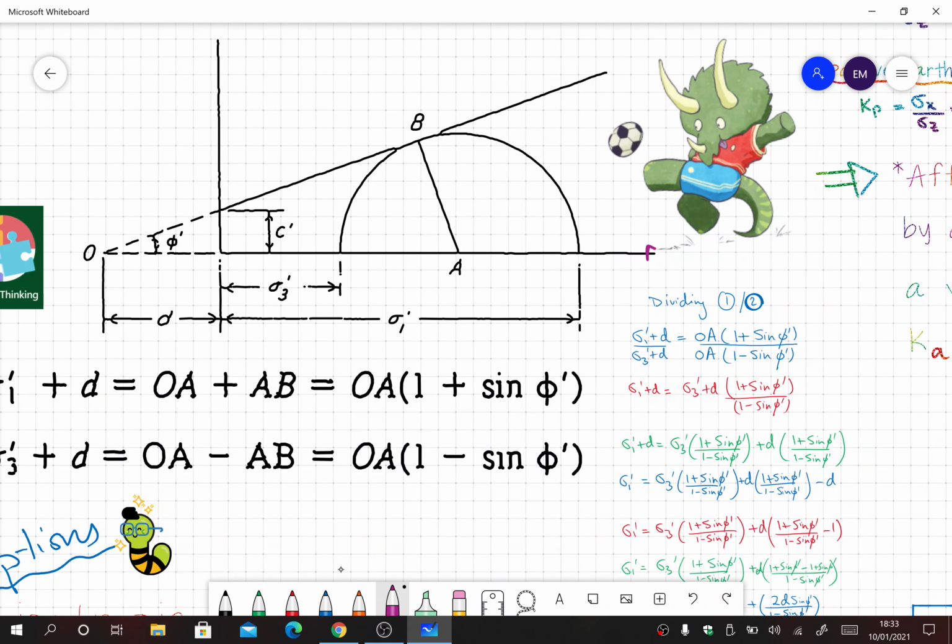So you see on the x-axis we have the normal stress and on the y-axis we have the shear stress. So we generally draw a Mohr circle. In this Mohr circle, it is touching the failure plane, the Mohr-Coulomb failure plane. So the y-intercept is c. We know that this is cohesion, and the angle of this failure plane is phi dash. We know that this value is the major principal stress and this value is the minor principal stress. I don't need to repeat that, we just discussed that in our stresses lecture.